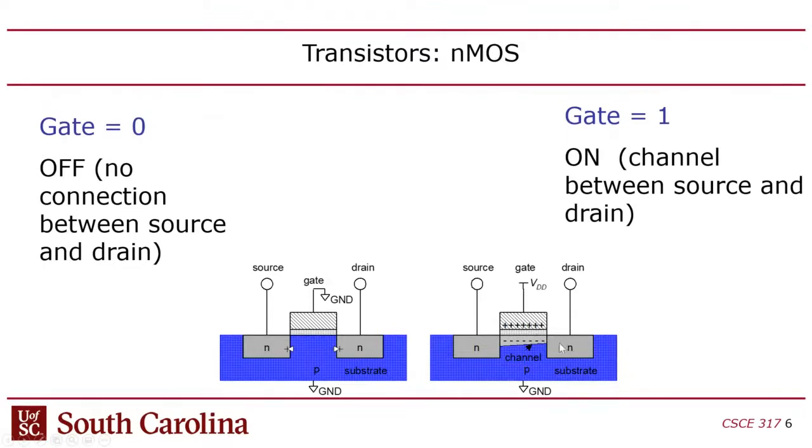But when the transistor is on and you start sending current between the source and drain, the voltage of the channel changes. It's no longer ground. In fact, what happens is that the channel voltage becomes the average voltage of the source and drain. Why? Because the channel becomes something different when the transistor is on. It becomes a conduit between the source and drain.